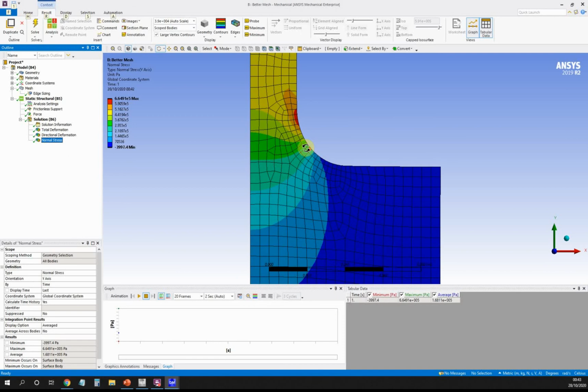a deal. Okay, so I think, and you'll also notice that as we've remeshed this more and more, our result has changed less and less, which is a sign of mesh convergence. Again, we'll talk about that in another video, but essentially what we're trying to do is refine our mesh until our result doesn't change anymore. And I think we've done that. We haven't gotten any better.